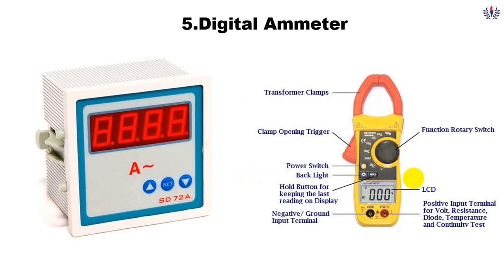The last one we are going to see is the digital ammeter. Here you can see the ammeter with the digital display. Here we have two extra components. One is the A to D converter. The analog value is converted into digital and it is programmed with the microcontroller. We have the binary value, that is, an encoder will be there, and a BCD converter will be there. In the BCD converter you get the value, and the 7-segment display. It may be used for both AC and DC.